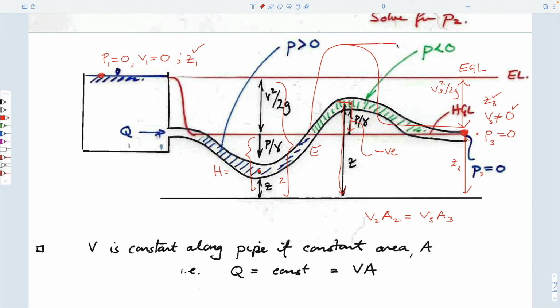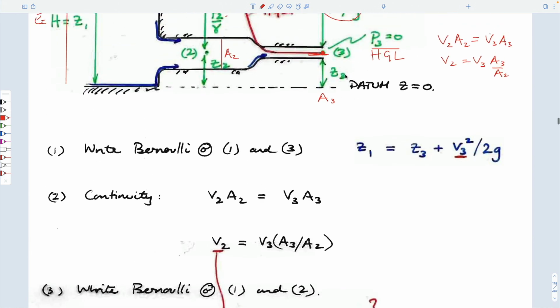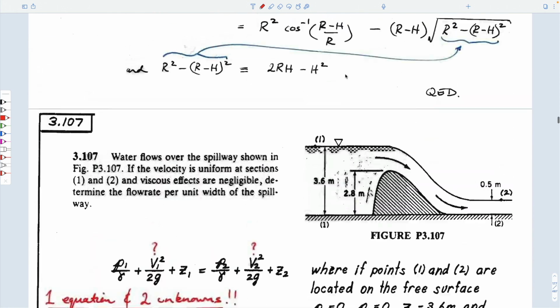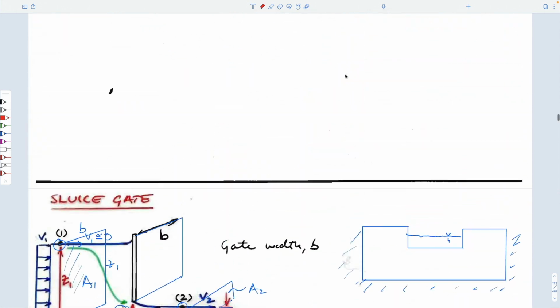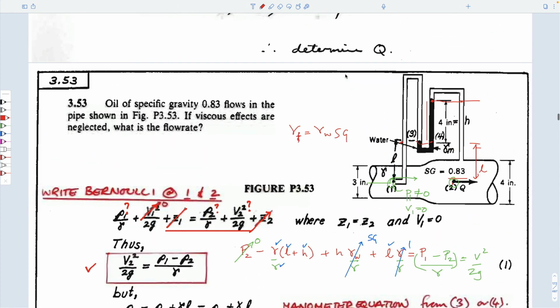And if this height here is equal to atmospheric pressure, then this water going up here will cavitate, because the pressure in this water, just like the case of the vena contracta that we talked about before, is so low that it will approach the vapor pressure and it will turn to vapor. It'll cavitate.